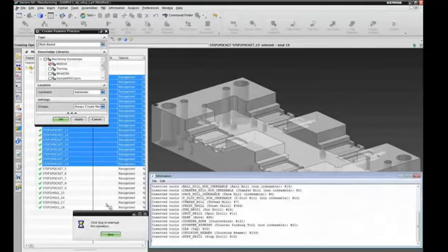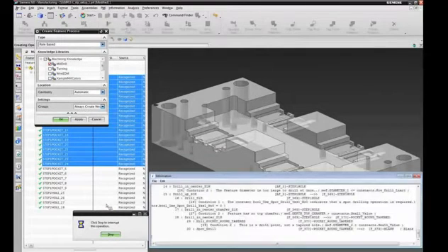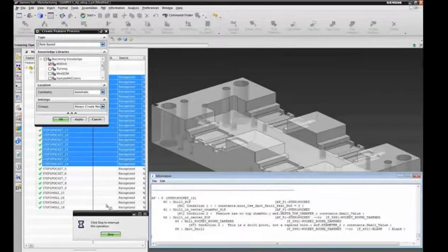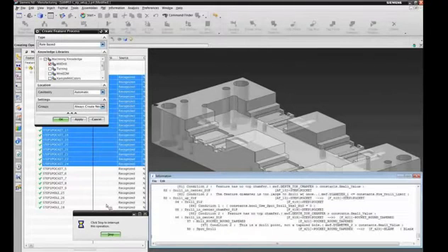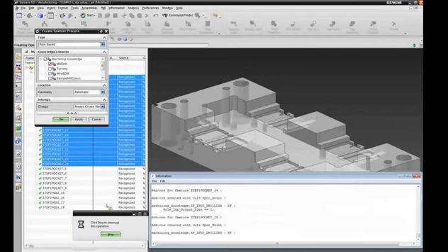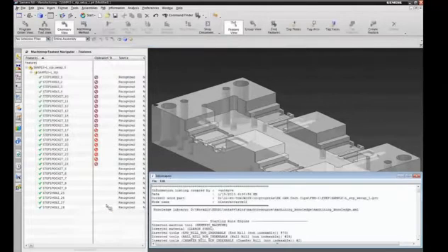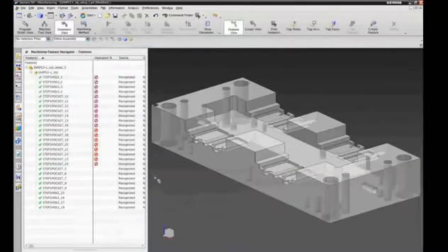You will notice that I have no PMI, right? All the holes are just regular holes. There's no thread. There's no dimension tolerances, so there's no fit holes. Everything is just regular holes. And since we don't know anything more about the geometry than just its dimensions, we will pretty much just drill and mill everything without using any real finishing operations, right?